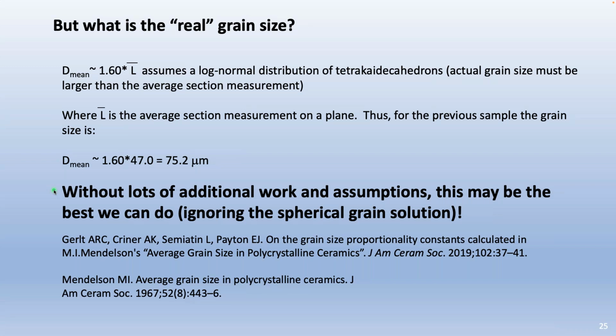Of course, ignoring the spherical grain solution. For the spherical grain solution, there is an analytical solution. It's been used a lot in foams, where people are trying to determine the distribution of pores in a foam, for example, where we know they're fairly spherical. From that, we can go back to a pore size and get a distribution of pore sizes, but we are assuming they're all spherical. With grains, we have to assume a grain shape. We don't know what that is necessarily. And so it becomes much more difficult to come up with a grain size distribution. And in some cases, unless you're going to do 3D data collection, you can't do it. It's just not doable.